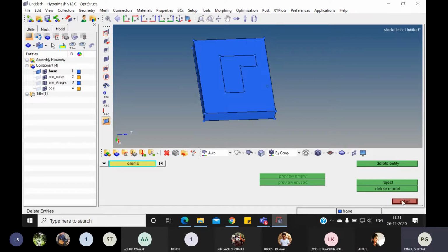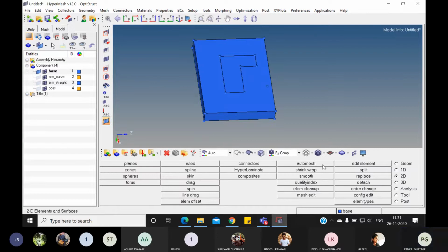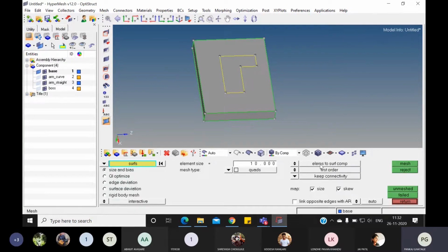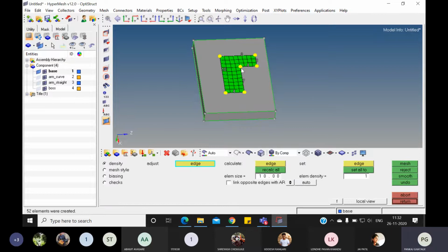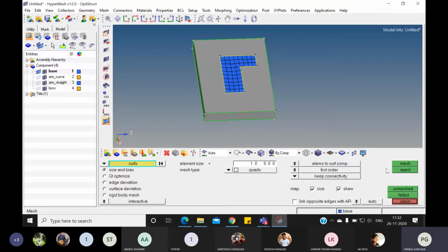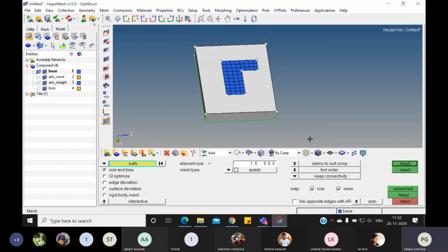So first of all, go to the 2D page, then go to the Automesh panel, and here you can select this part, mesh it. I will keep as 4, 7, 10, 8, and 3, and then return. And one more thing is that you can select this surface. So I am doing only a surface mesh here, 2D meshing, and then I am going to convert that same pattern to the 3D mesh. So that quad will be converted into hex and tria will be converted into penta.